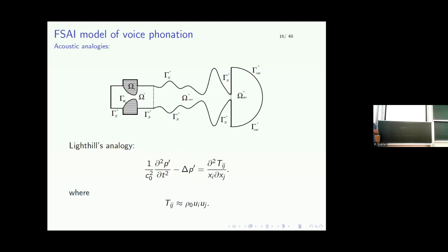So typically when we are solving the acoustic part, we have a 0 on the right hand side, and we are just propagating sound which is created, for example in vibroacoustics, by a vibration of the structural surface, and we only propagate the signal created at this vibrating part. But in aeroacoustics, we need to include also some sources. Okay, there is a missing partial here. So this is the second mixed derivative of the stress tensor, which is the Lighthill tensor here. And for the case of low Mach numbers, which is our case, this Lighthill tensor can be approximated by the convective part of this tensor.